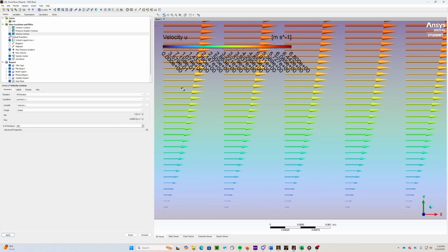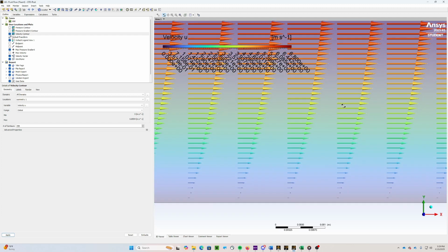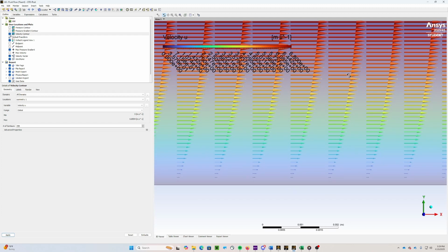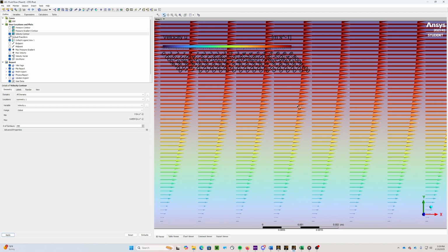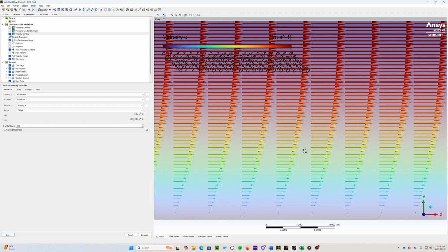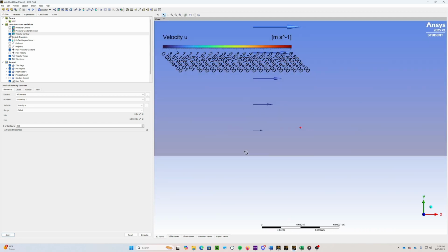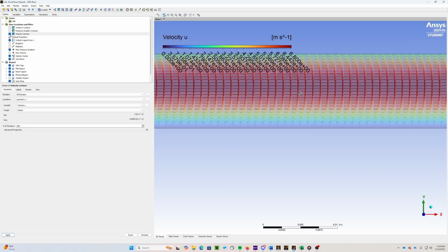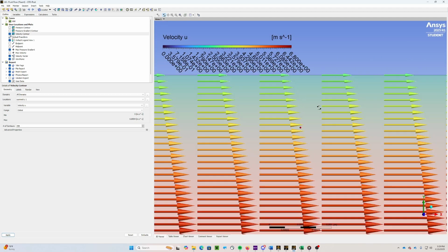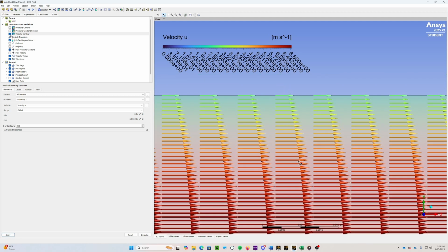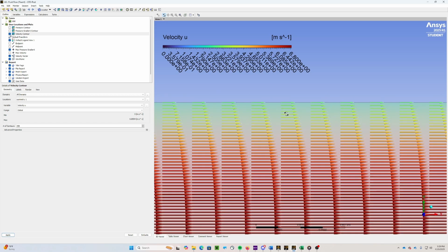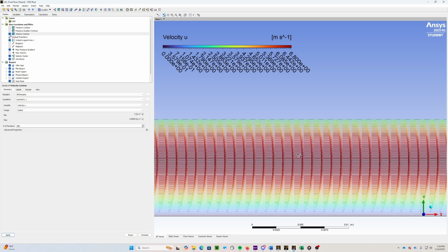So then after hiding the contour lines, you can get a cleaner look at your boundary layer. You can see here, I move it around a little bit, zoom out. You can see it tracing on up to the middle. This is on the bottom plate, so it's stationary. So down at the bottom, obviously we have 0 velocity, a stationary plate. However, if we go up to the top, we can see a different velocity profile because it's actually starting with an initial velocity of 3 meters per second. So slightly different, but that's because it's the Poiseuille Couette flow. So those are your two different boundary layers.